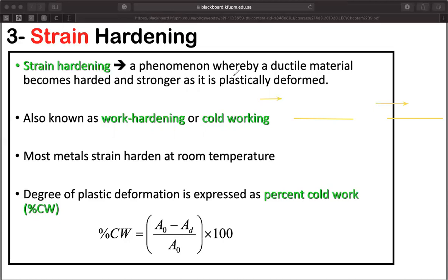You got a dislocation that is moving on the slip plane. For sure, you need a smaller amount of stress compared to this situation where you got more dislocations active to move. So here, the needed stress will be less than the stress that's needed in this case.